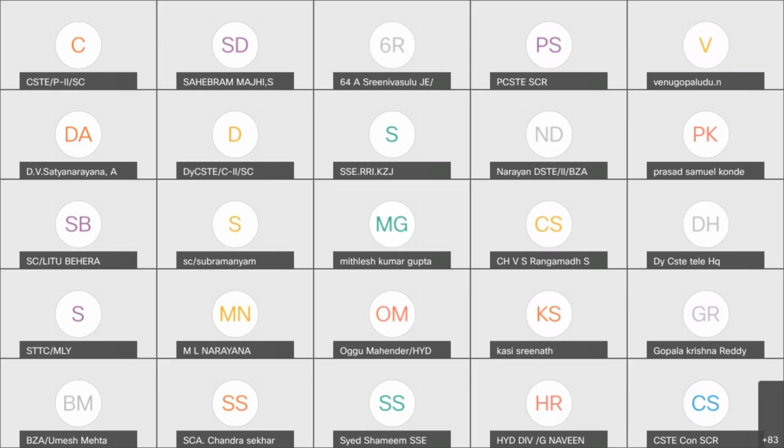Can anybody from maintenance and construction comment? Sir, for this, we are providing bushes in the slides also, sir, for arresting play, like the previous non-improved TWS point machine, sir. In the rod's lug, there is a big hole coming now, sir. For this, we are providing insulation bushes to arrest the play, sir. Okay, understood. Now, anybody else wants to comment on this?